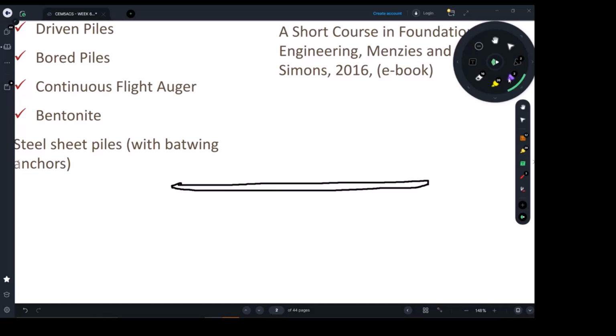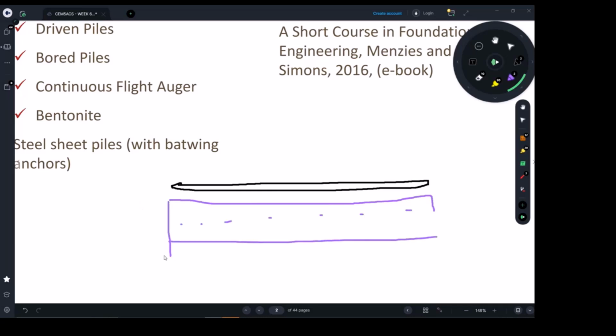So here we may have, with this purple color, a stiff clay, which will definitely be doing all the job. Then you've got basalt, and under the basalt you've got rock. This is a very safe, strong ground structure. You may have a little bit of sand at the top, but it's going to be cleaned off. Then you have stiff clay, then basalt with some floating rocks, then rock. This is really the best layers of soil below a road or even a building.